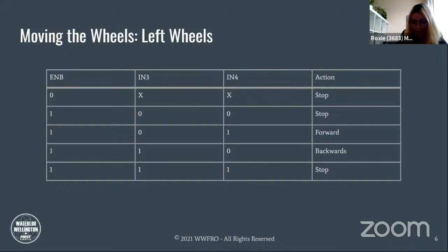Okay, well, I guess. I'm not 100% sure on this, but I think if your IN3 and IN4 are 1, the motors will brake, whereas if there's 0, the motors will coast. So they're both off, but one of them is kind of off and lets it glide, and the other one's off and puts the brakes on, I think. Oh, I see. I think that's the difference between 0, 0 and 1, 1. All right, well, there you have it, folks. I didn't go into that in this tutorial, but that's a good tidbit to know.